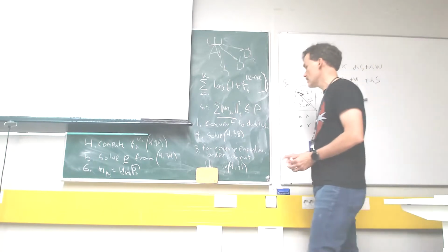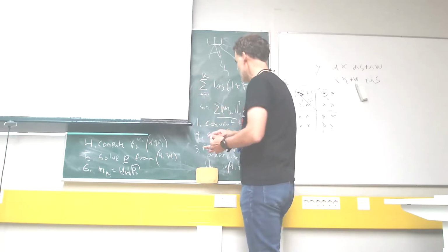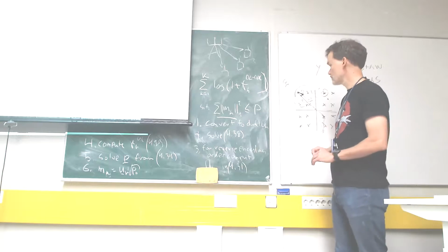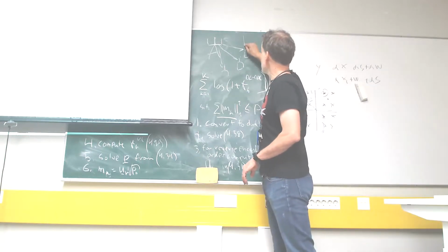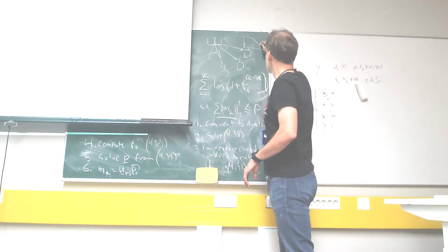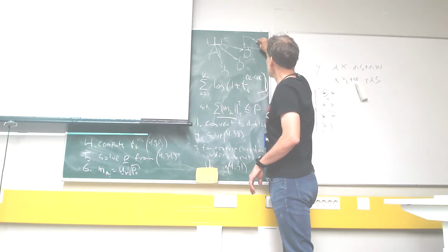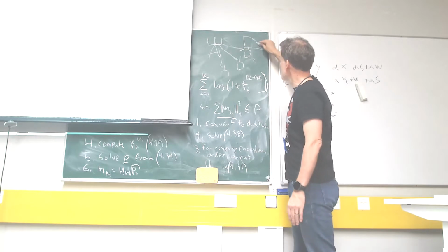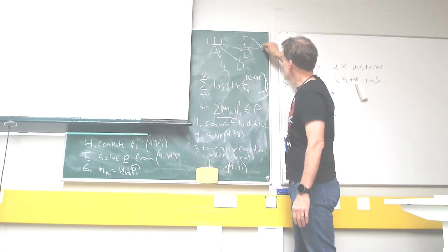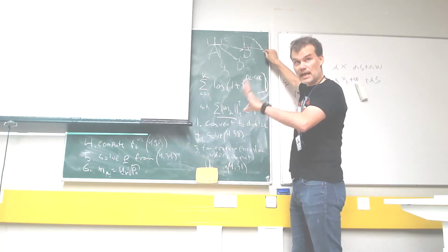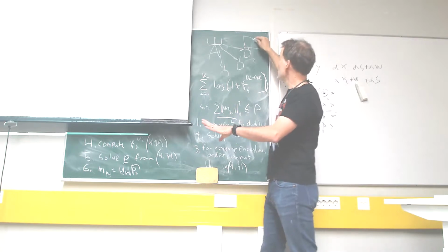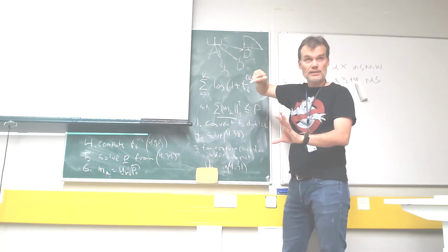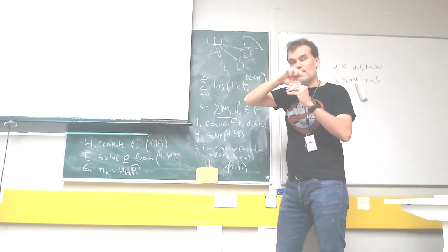Obviously, later when we discuss the rate region, the encoding order matters. You recall that in the two-user rate region, when you are in this region, user 1 should be decoded last, and here, user 2 should be decoded last.